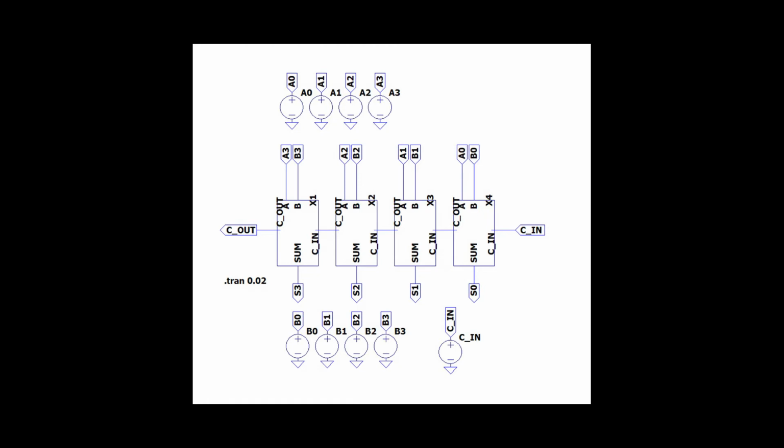Next, the 4-bit full adder circuit is constructed to perform 4-bit binary addition. Carry in is usually 0 as the first input to the first full adder, FA0. Meanwhile, A0 and B0 are also inputs that will be sent to FA0 to produce the first sum S0 and carry out CO1. S0 is the least significant bit, LSB, of the 4-bit sum.